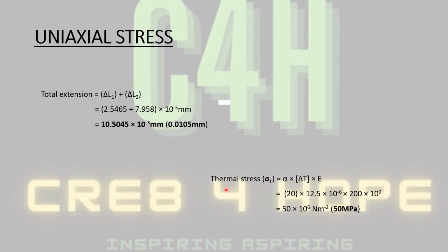We're also asked to calculate the thermal stress if the component experiences a temperature change of 20 degrees C. From a previous lesson, I think relating to chapter 4, when we briefly talked about thermal stresses, we can calculate the thermal stress by multiplying the coefficient of linear expansion by the temperature change, or temperature differential, by the Young's modulus.